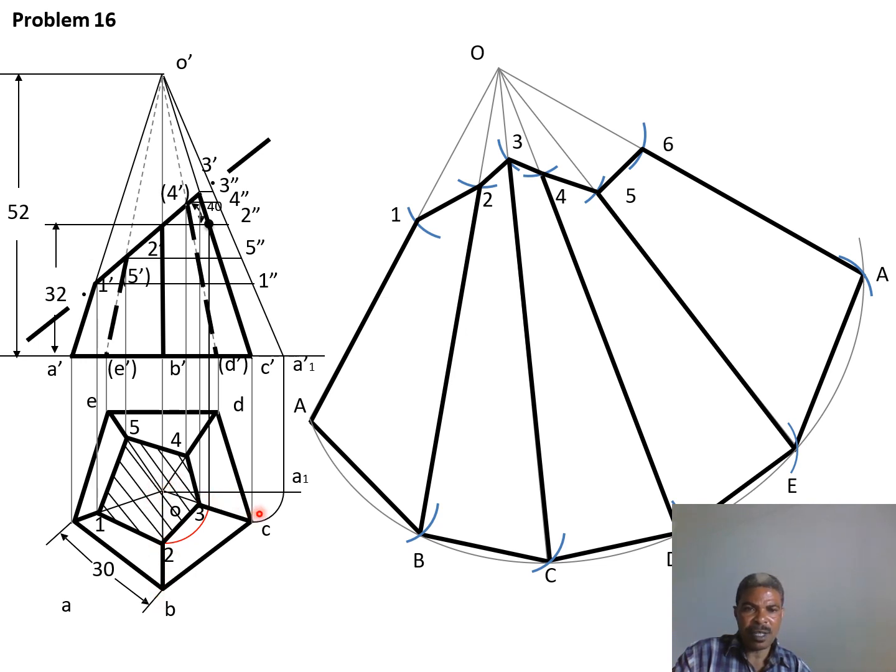These lines are very, very important here in order to lead you in projecting the points back to the line of truncation. After you have drawn the base of your pyramid, you need to draw lines until they meet at the center from each edge.